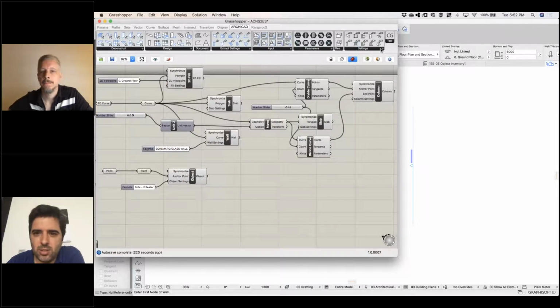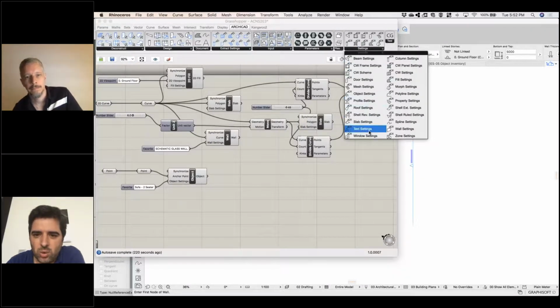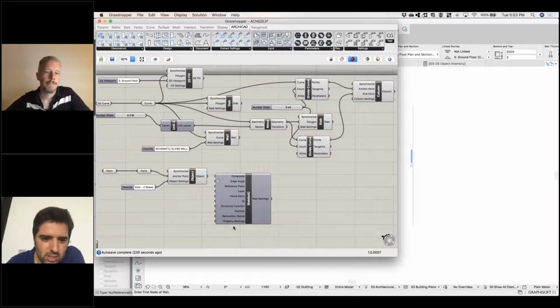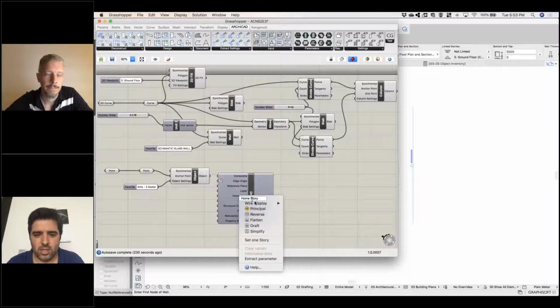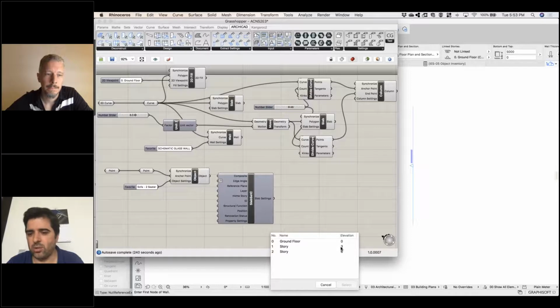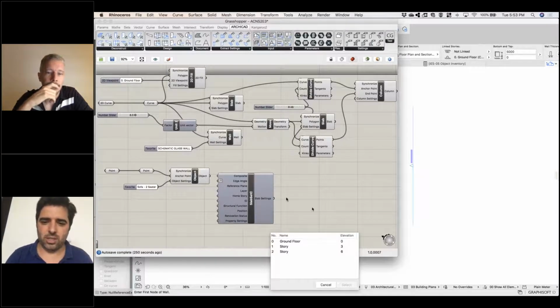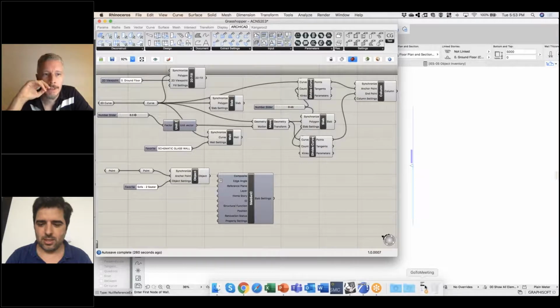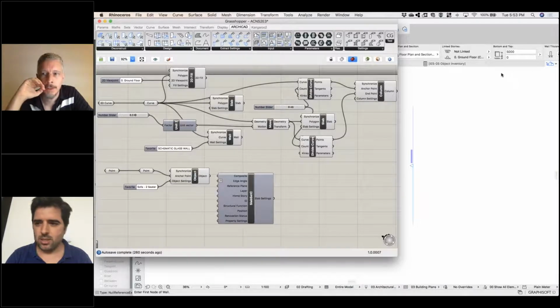Let me see, for example, I will place a wall setting or a slab setting. And you can see that we can have the home story as a setting that we can add here. So I can just go here to the home story, set one home story, and I choose which story it belongs to. So I can force it. By right, it should end up somewhere within the floor range. If not, we can force it by using the slab settings node. If slabs are being repeated vertically, they can automatically be made relevant.